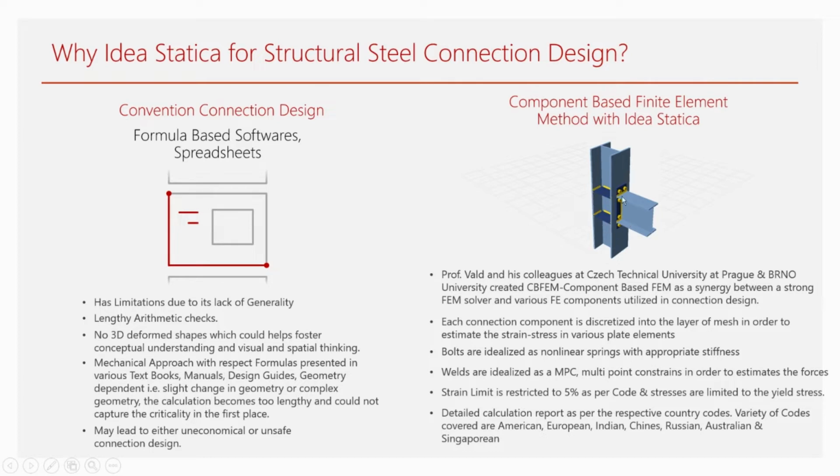The components are the end plate, stiffeners, doubler plates, bolts, and welds. All these components are discretized into a layer of mesh in order to estimate the strain and stress relationships in various plate elements.